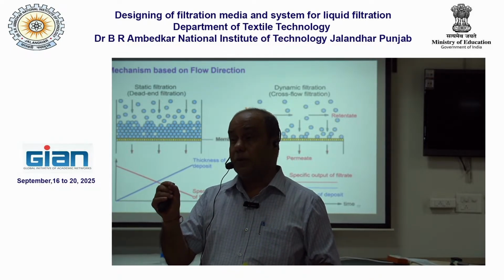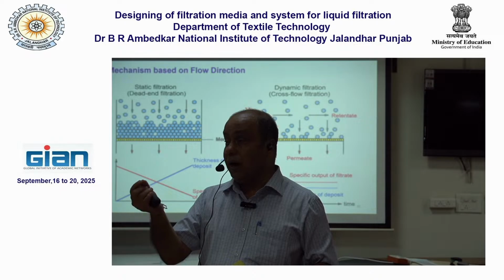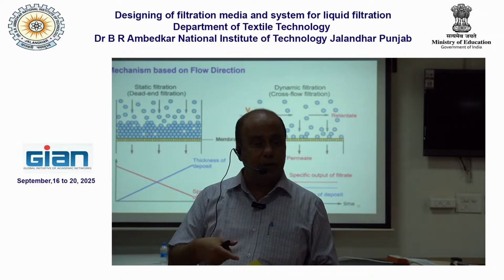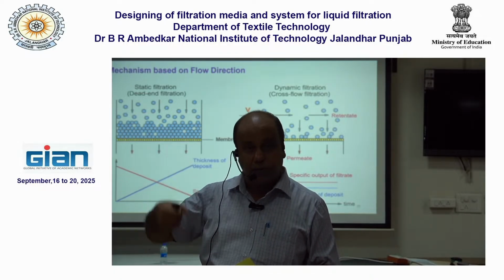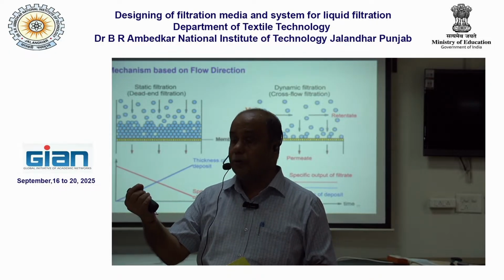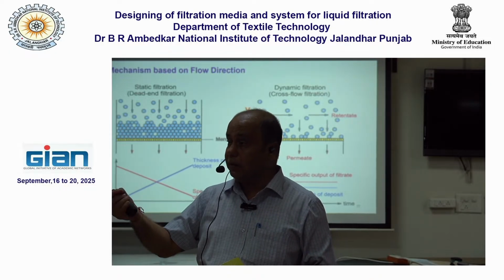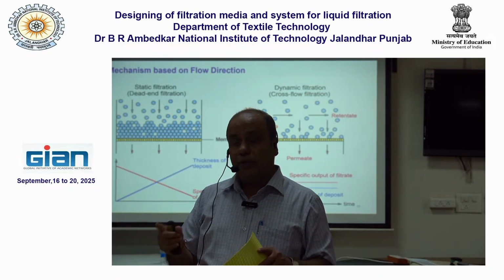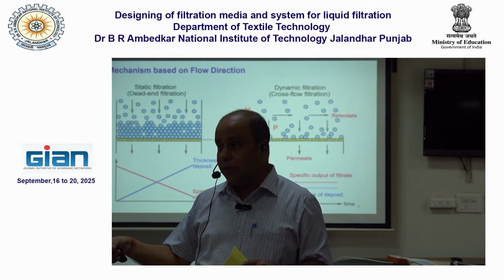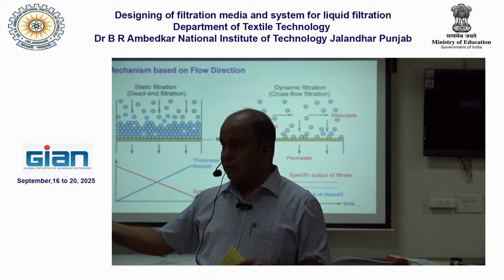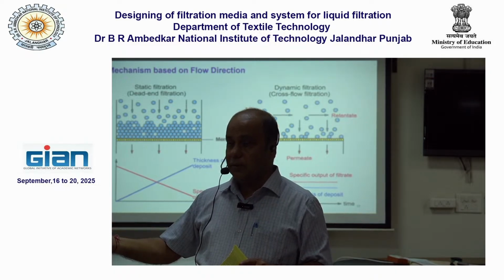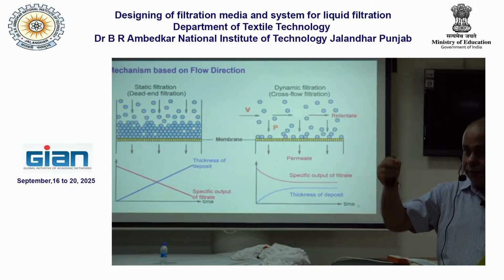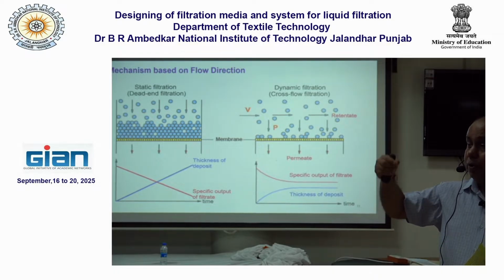If you want to capture virus, bacteria, okay, ionic matter, for example, in reverse osmosis, why do you need so much high pressure as compared to ultrafiltration? You need very high pressure in the case of reverse osmosis, because the ionic matter you will have to remove. That could be smaller than virus, bacteria, that you want to remove. That's why you apply a very high level of pressure, because nothing comes out free. Reverse osmosis obviously can remove something, but at the cost of energy, okay, at the cost of energy. So whenever we are talking about finer particulate removal, that always becomes challenging. The finer the matter, okay, the more and more challenging it is to separate.